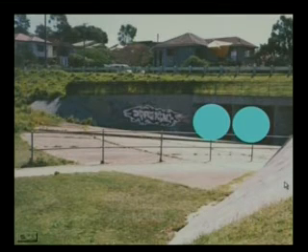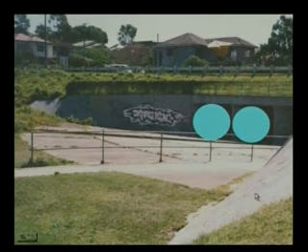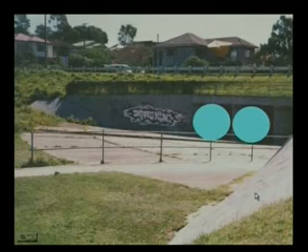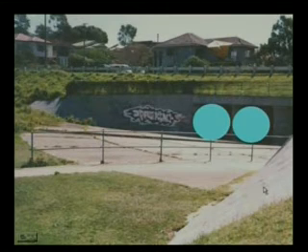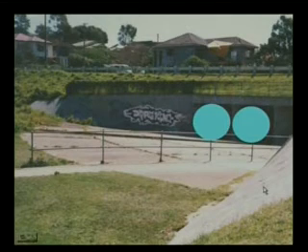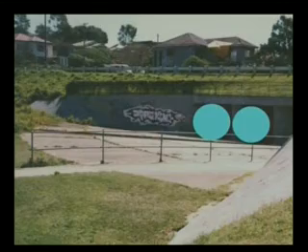Such slopes are there on all 4 sides. One here, 2, and 2 similarly on the other side also. So there are in all 4 slopes. For the purpose of calculating quantity, we assume that they are 1/4 of a cone. You just cut a cone into 4 parts. Each corner would make 1/4 of a cone.